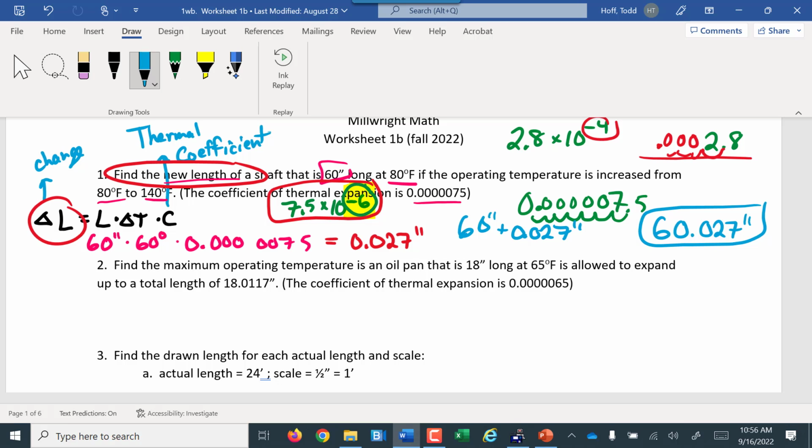The bigger thing is bridges. You ever see in bridges, you're driving along and you have that like 2-inch gap where you have these metal plates? Those are expansion joints. Bridges will expand, again, 8 to 12 inches, depending on the structure and the length of the bridge. Without those expansion joints, those bridges would actually heave up 2 or 3 feet from where their normal elevation would be. It's really amazing. That's why you see concrete, in really hot sun, or the pavement on the roads, the blacktop will have big busts, because it'll expand enough that it'll heave up and crack through.